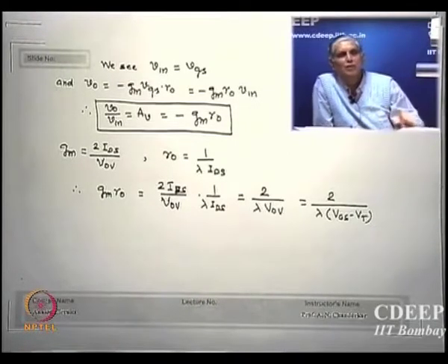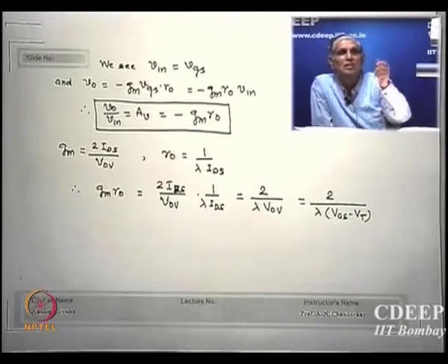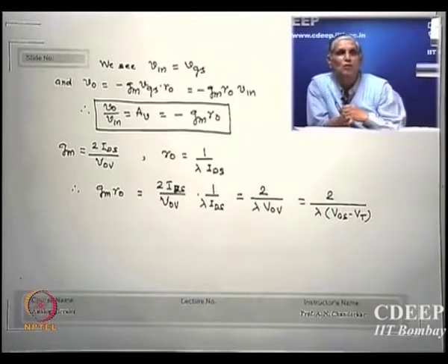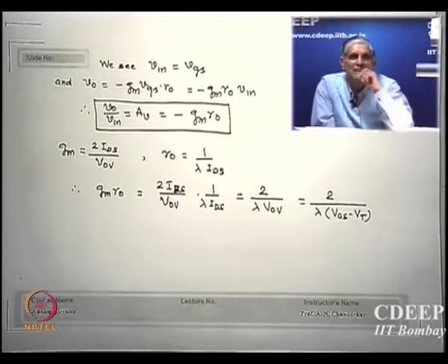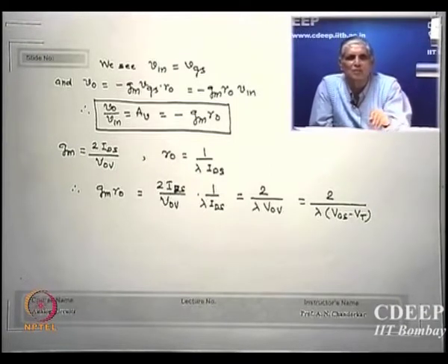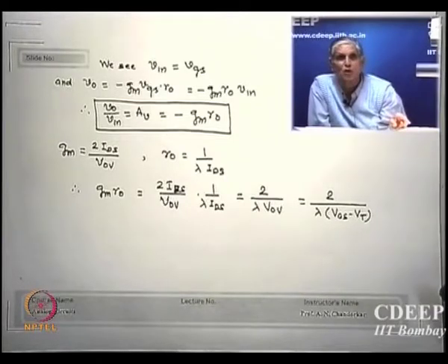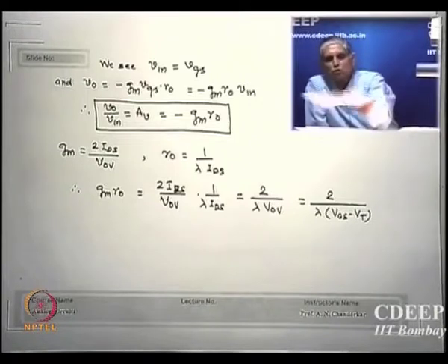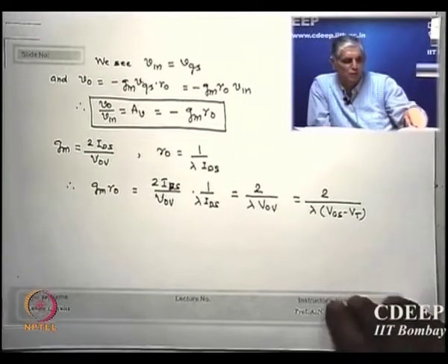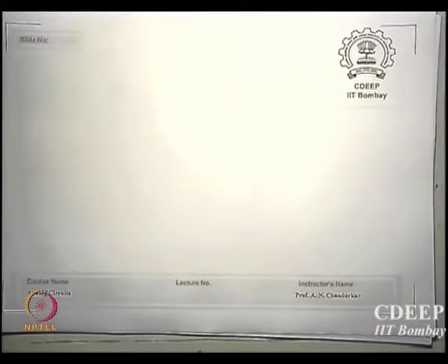So why am I giving you this? Because when I am making a circuit on a board, how do I choose a transistor from the box they give you? I say I want so much gain, so let us see what intrinsic gain I can get. These values will be specified in the manual data sheets. So you find, okay, this is 500, that much is good enough for me. This has to be done beforehand, before I actually go on the board. Certain things, as we do experiments, we ought to know a priori, and these are the ways a priori values are evaluated.